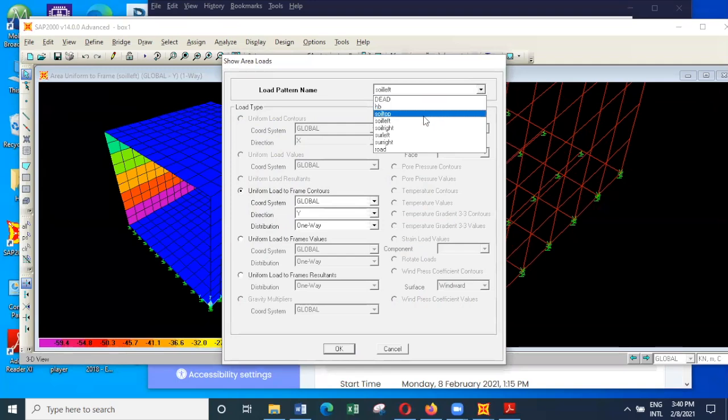You can't see anything called the base. The reason is if you have a load directly acting on the base, it will be transferred directly onto the soil without causing any bending moment. So we don't have to consider any loads that are acting on the base vertically downwards. Whereas, we have to consider the effect of all these loads distributed by the base acting as a raft. So those should be considered.